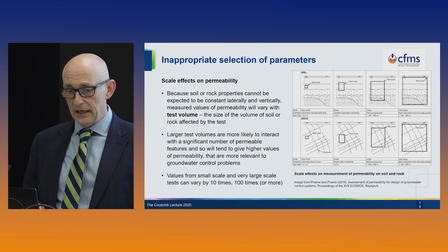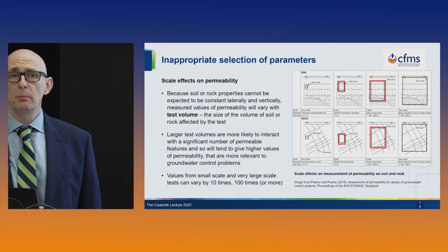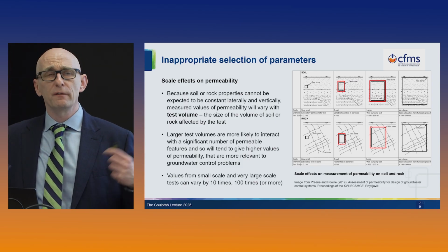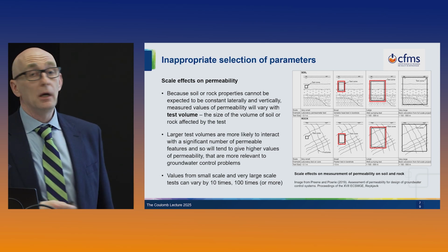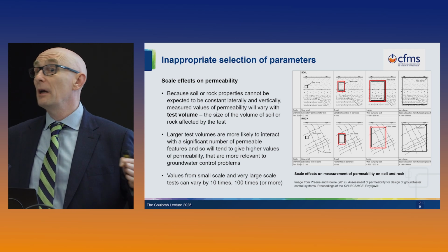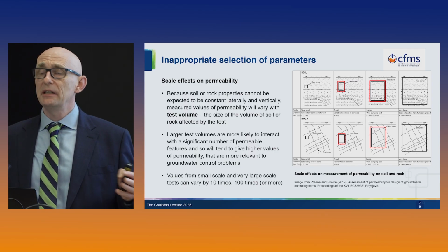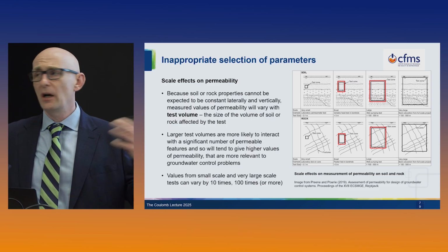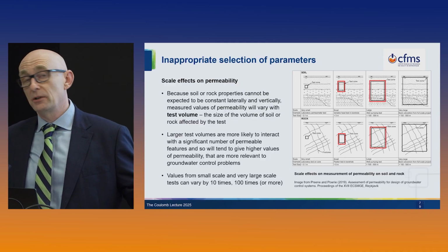So if we think of a test in a borehole, this would be a variable head test, what we call a falling head test in a borehole, or maybe a packer test like a Lugeon test. That might influence a zone of soil maybe 5 meters across. Whereas if we carry out a multi-day well pumping test where we pump, say, for 5 days at a high rate, that might influence a zone of soil hundreds of meters across.